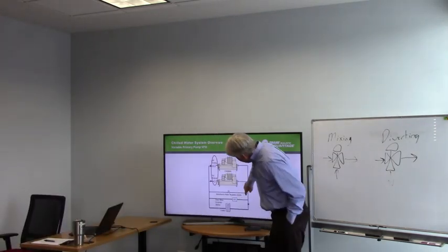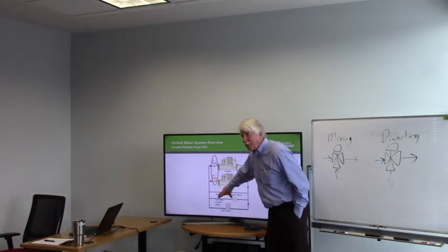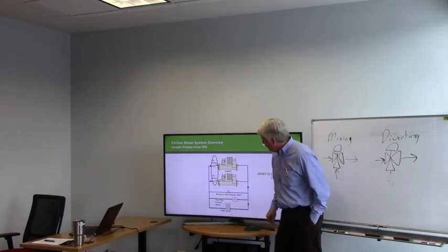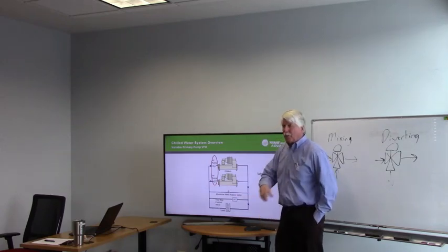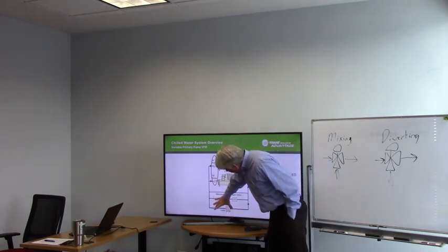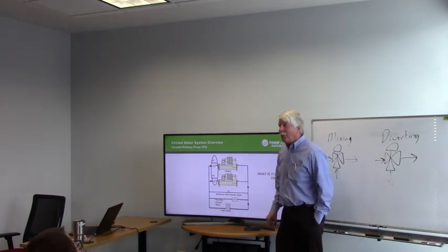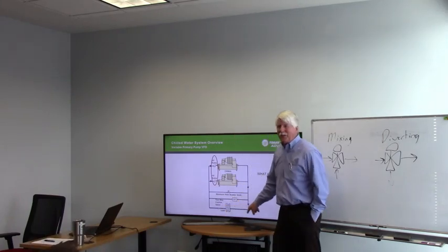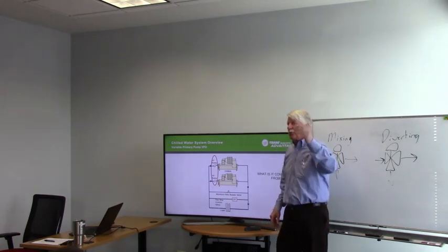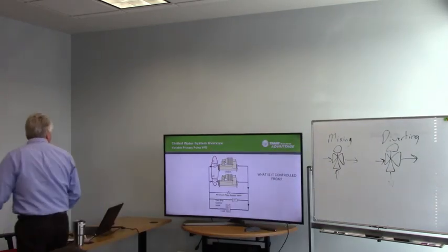If we put the DP right on this side of the bypass, in other words, right here, and there's no loads out here, this DP isn't going to change much as it happens out here. So you might say, Tony, let's take your argument to the extreme like you do. What happens if I put the DP across the last piece of equipment? Well, it'll only vary flow as that one valve changes. Okay? So a long time ago, somebody said about two-thirds of the way seems to work pretty good. So that's what you control that on.